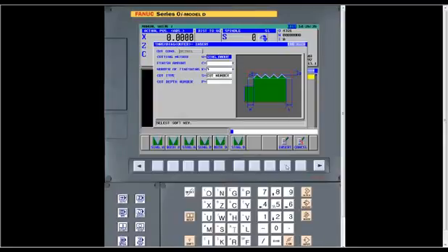But you've got six different ways of feeding into it. The finish amount, you can leave a particular amount of finish stock or a particular number of finishing passes. And then also you can have cut type. You can have number of passes or depth of cut. Those are your 2 choices. I'm an old engine lathe guy, so I'm used to cut number. I've got in my head how many passes I want to take, so I always use that. But some people always think in depth of cut. That's all right, too. It'll work both ways.